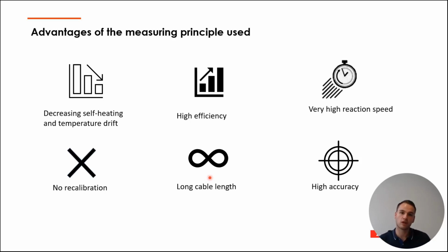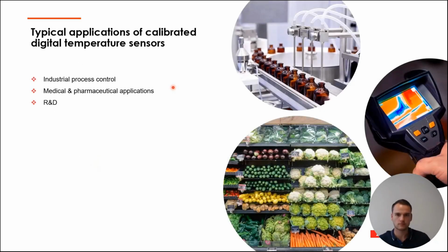But if you have 100 ohm resistance and you add a cable with 5 ohm resistance, then the accuracy is really low because you add 5% error, and basically the sensor is really inaccurate with a long cable. And in general, the sensors have a really high accuracy.